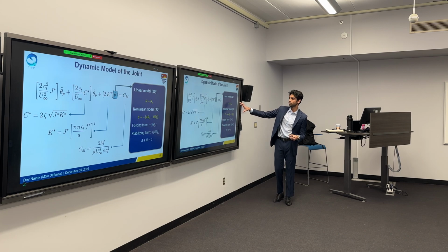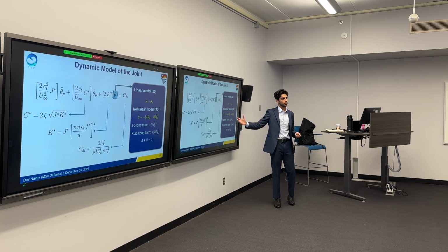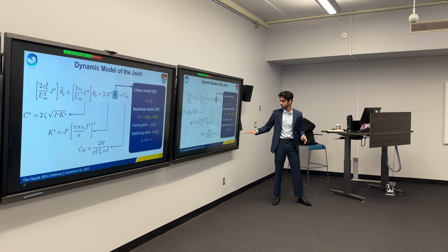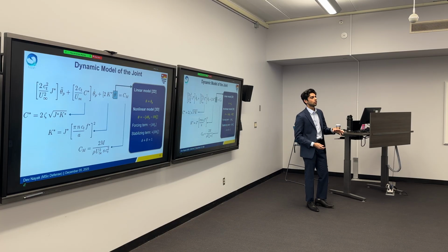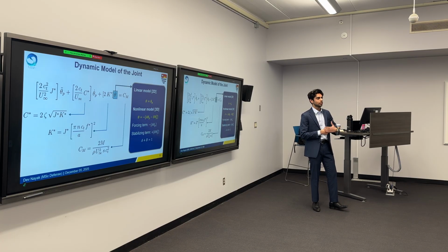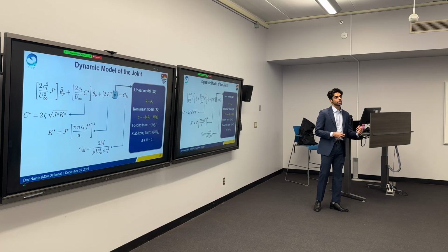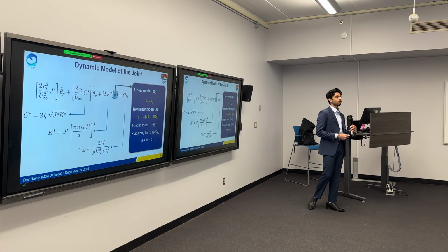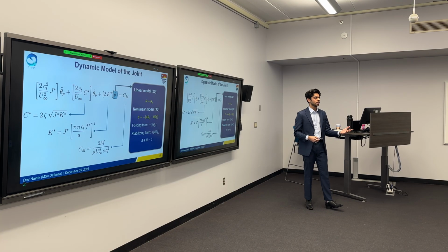So for the linear model, we have just used the pitching angle in the equation, but for the nonlinear stiffness, we incorporated a forcing term and a stabilizing term. So one term basically will make sure the pitch of the caudal fin goes to a larger amplitude, whereas the other one, the cubic nonlinearity, kicks in and will stabilize the system when it reaches diverging oscillations.